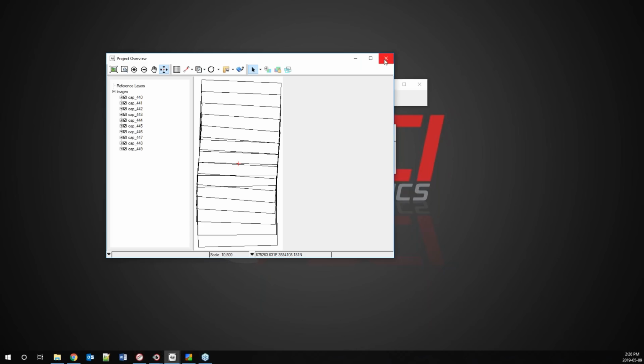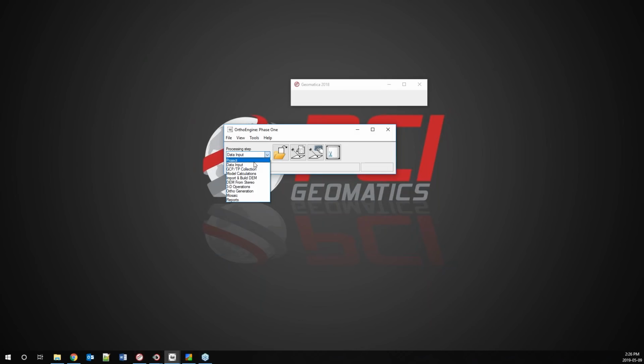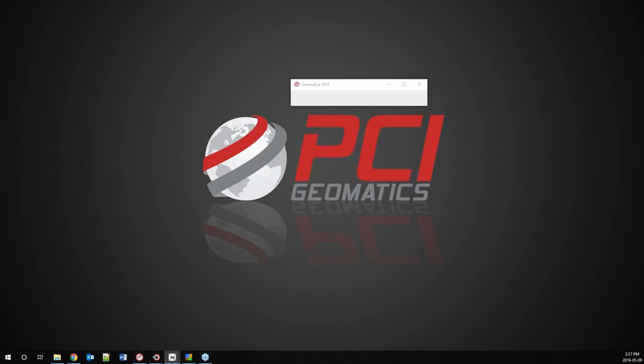Now, I'm going to go to the next processing step, which is our GCP and tie point collection. Here, we can collect automatically or manually ground control points and tie points and utilize a residual report to view the overall summary of the absolute and relative accuracies of the model. But for purposes of this webinar, I'm actually going to go to another project file where I've already collected the tie points and the GCPs, where I've already improved the aerial triangulation.